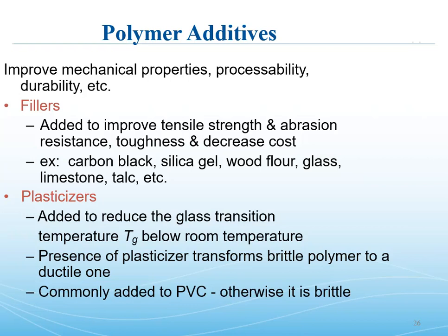PVC is classic for requiring plasticizers. Most vinyl polymers, especially those used in thin films and plastic bags and sheets, make heavy use of plasticizers. Something to remember, given that most of these are powerful release agents. So if you're using a thermoset as an adhesive, be aware of the ubiquitous nature of plasticizers in all of your surrounding thermoplastics.